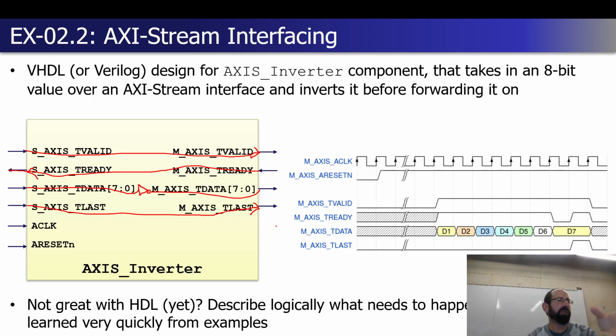So from the render output's perspective, the logic should still look the same. Take base address value, take XY from my AXI stream interface, add them all up together. That's my output data that I'm writing. Is that what you were getting at, or does that answer the question? I was just asking if you just switch the base address. Yeah, you have to wind up just switching the base address. I think the driver has to do that.